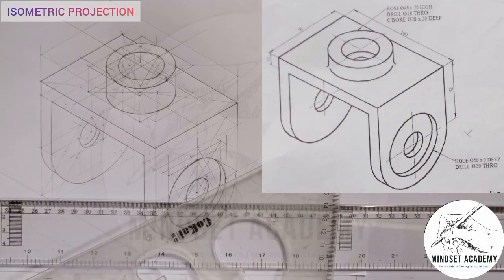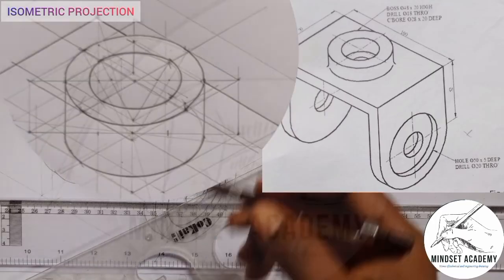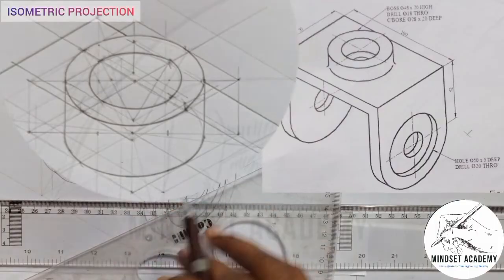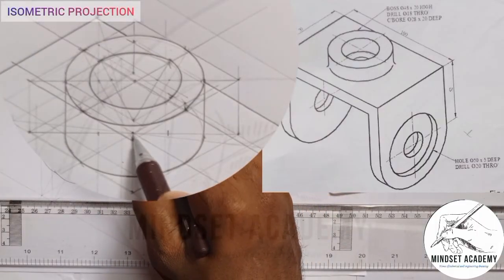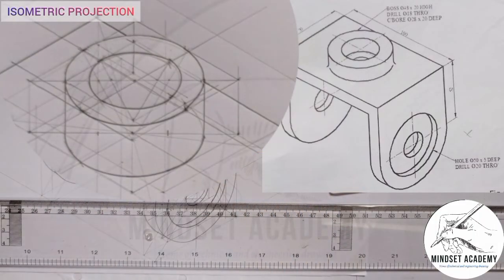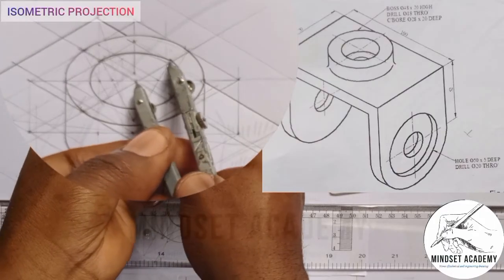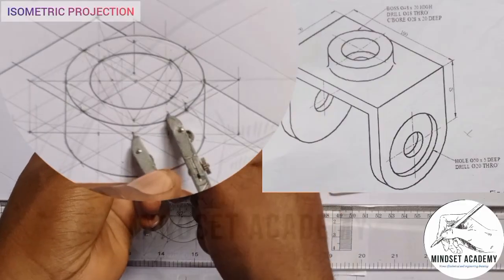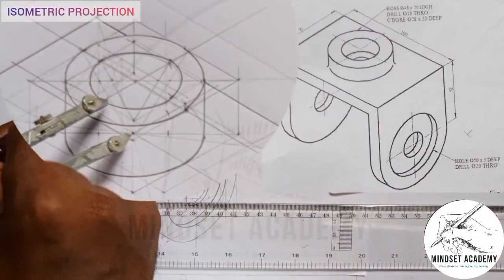So the next thing is we have a drill 18 millimeter through. So we actually have a drill in. So you measure, don't forget the same level. It is 20 millimeter in. At this same point, I'll measure, right? So let's just do that and see. You just pick up your compass and you measure from this center here to the center here. You can see that. And you come to the center here. You mark here